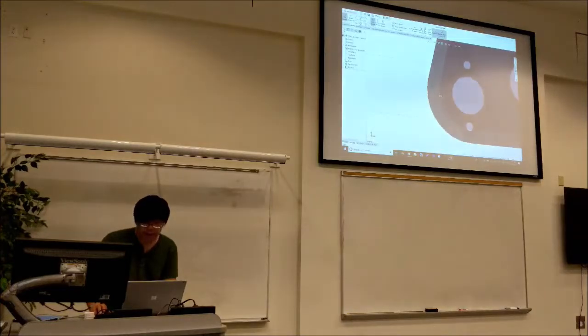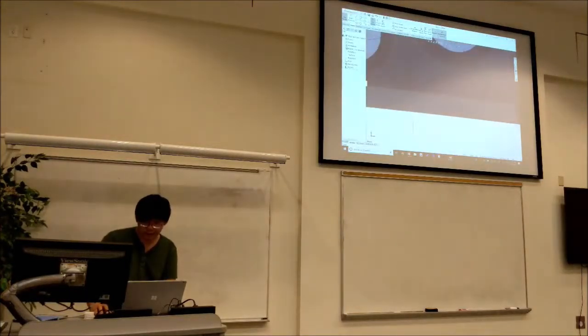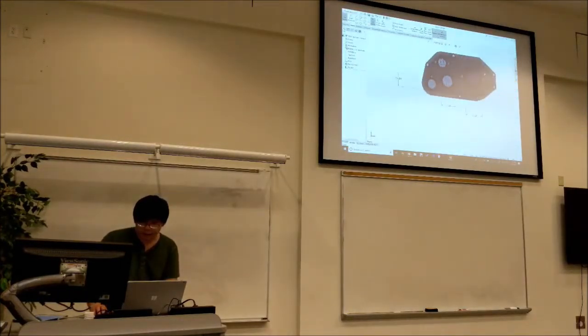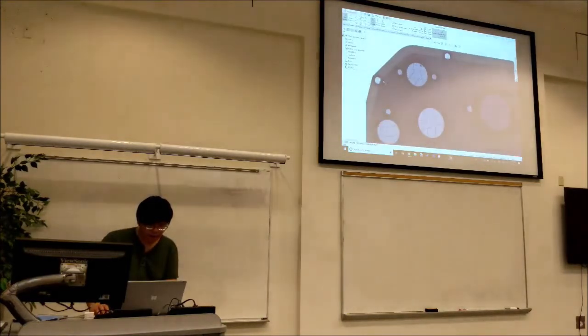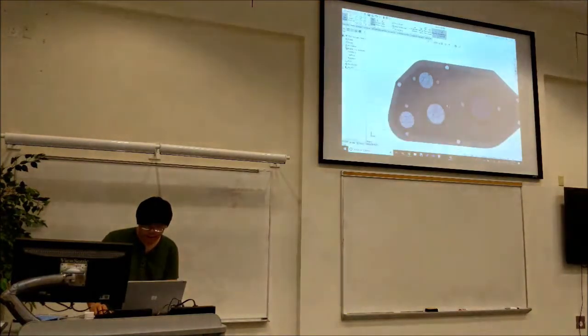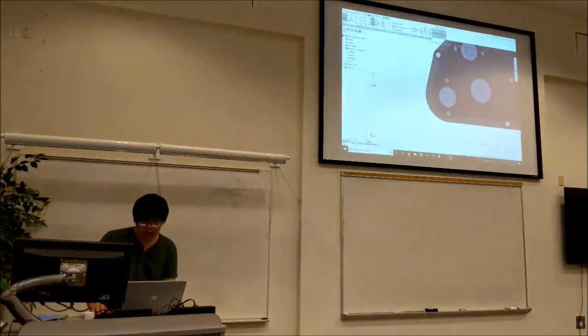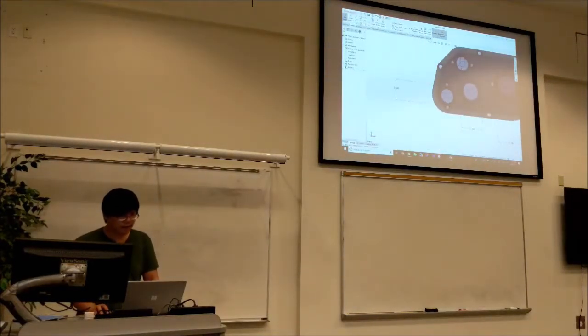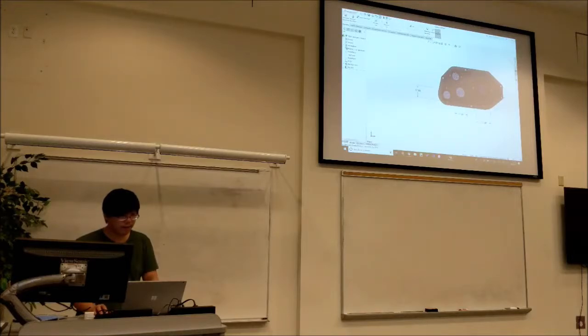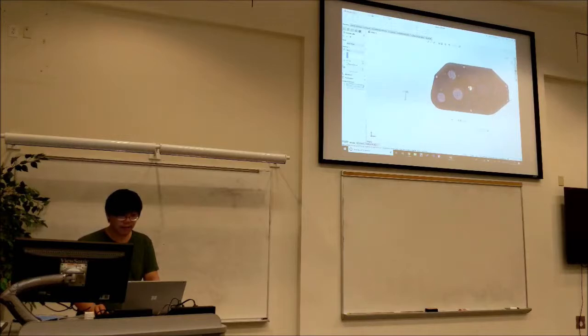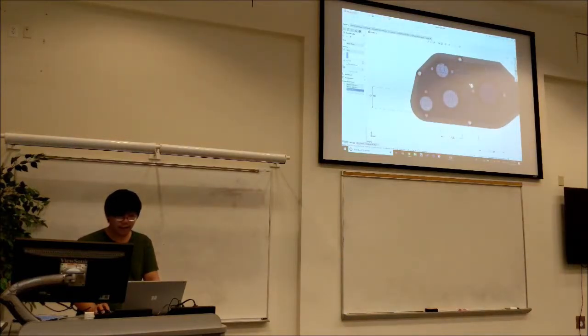And then that typically happens when it's not a straight edge, because it does it correctly here. So let's just check to make sure all of that is correct. Yeah, so it's looking okay. So now if we go to features, we can do cut extrude, and then we can select all of our contours, right? So if I select that, and all of our closed contours.